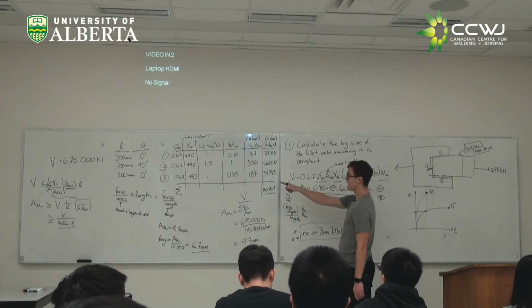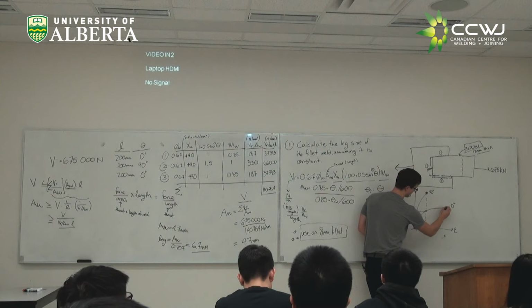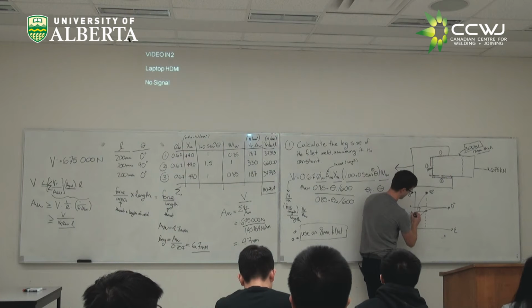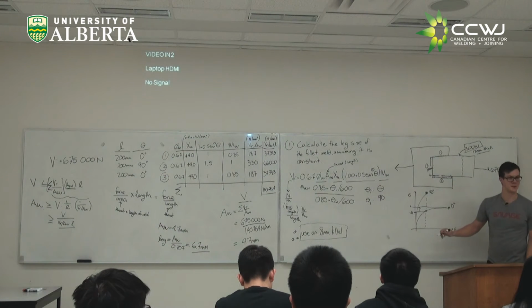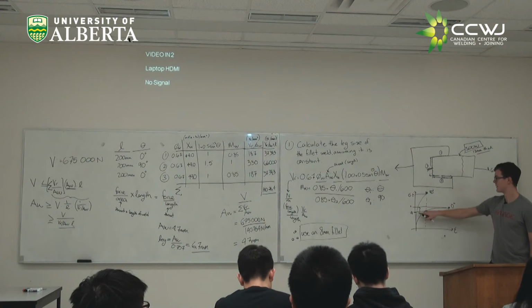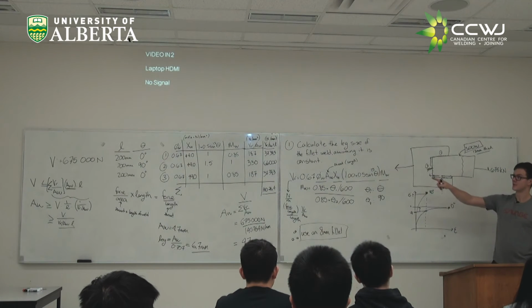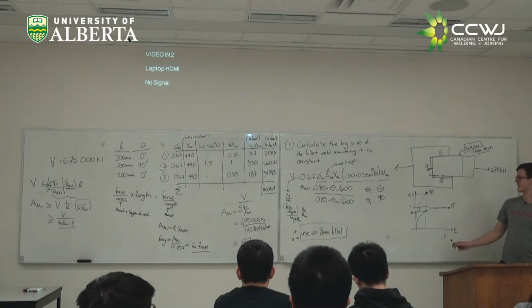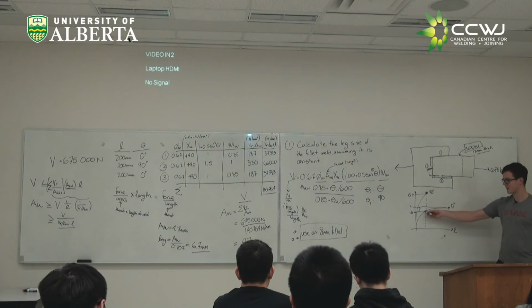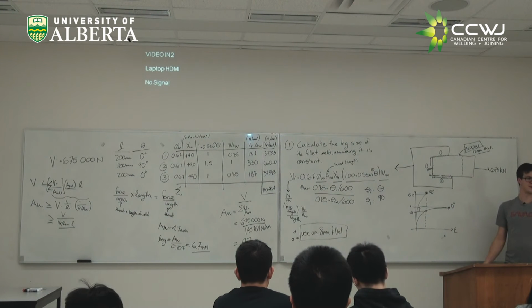Now that 0.85 is considering the fact that this limit here is roughly, if you call this 1, then this is roughly 0.85. This is done from experimental work, but it's considering the fact that if this is 1, this is 1.5, and this is 0.85. Can you see where those numbers now come from? So this fails at stress of 1.5. This would fail at a stress of 1, but because we don't get all the way to its failure, we consider it to only have a strength of 0.85.